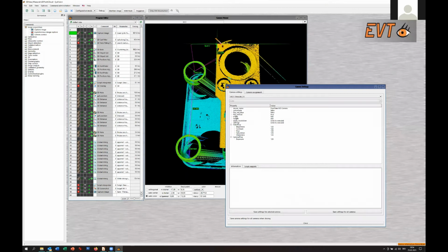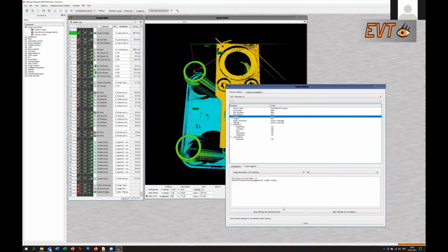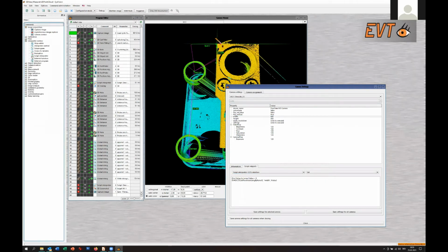If you want to control everything in the software or from outside of the software, you have the option to control each of these either with the camera control tool or, and this is really powerful, the built-in script interpreter. This is its own tool. You can find it here in interpreter control, script interpreter. You can program it in Basic syntax language, and you have access to everything.